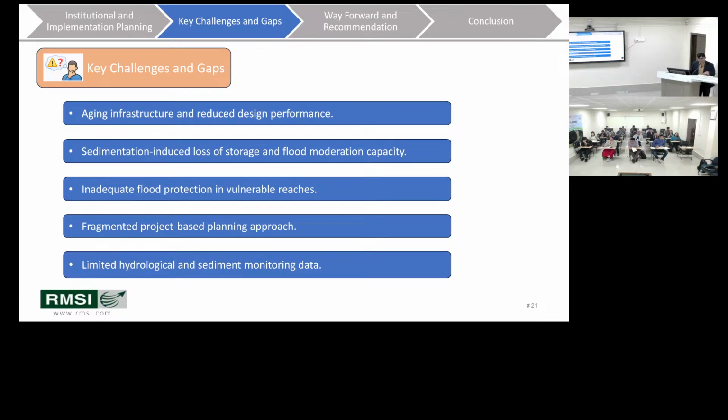The challenge is always there. I should emphasize here, this is the major challenge in data collection. I am saying we should have 30 years of long-term data in hand, but you will never get this continuous data. You have some data gaps, and problems like hard copies, scans, and even errors in data. So you should have a clear mechanism to remove those outliers, considering some statistical procedures, or you should consider some judgmental procedure, and discuss with the experts.